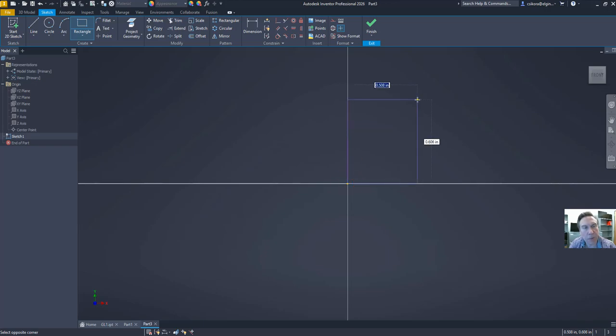Move your pointer to the upper right, and you'll see some dimensions appear. Like for the width of the part, mine is around a 1/2 inch or so. We actually want that to be 3 inches. So instead of clicking in there and typing in a value, notice it's blue. That means it's highlighted, ready for you to add one. Type in 3. You don't have to type in 3.00 if it's just zeros. Now, to get the next one, we want that one to be 5 inches.